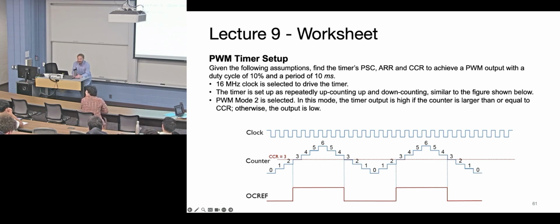Because of those awesome designers, right? Prescaler is whatever value you put on there plus 1. So that's your division value. And I believe they've done that so that you can't accidentally put 0 in there and stop the clock from coming through. I think that plus 1 is just an arbitrary choice by the STM32 designers.